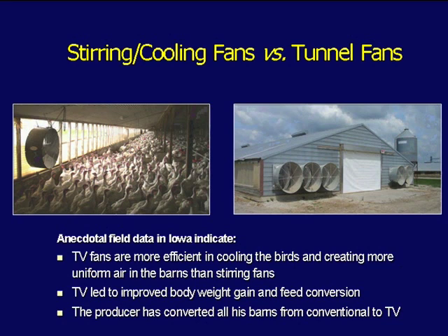String fans or cooling fans, I kind of talked about this. Turkey folks pretty much use a lot of the string fans in the Midwest. In a recent study, we actually converted a barn into a tunnel fan barn. The data is somewhat anecdotal, but according to the producer, the tunnel fans are really more efficient in cooling the birds and creating more uniform air throughout the barn. His records indicated the birds did have improved weight gain and feed efficiency. As a result, he has decided to convert all his barns from natural ventilation or string fans to tunnel fans.